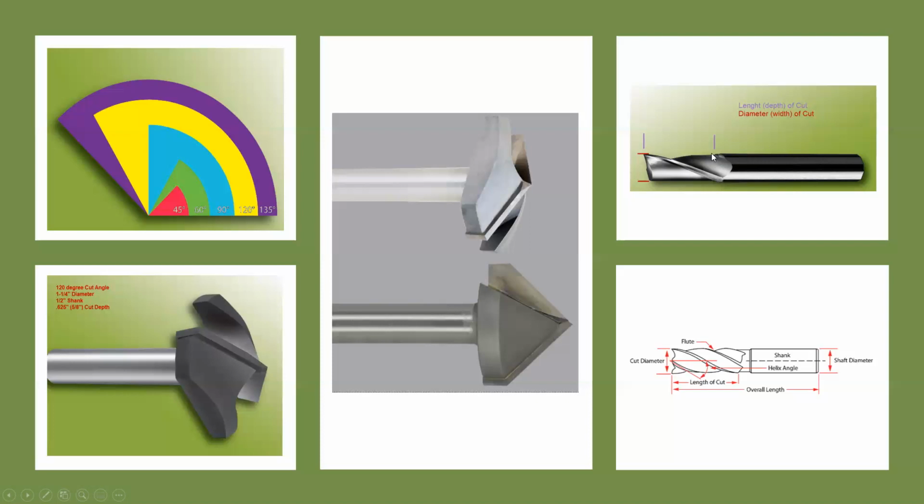Okay, but the cutting length or length of cut is always going to be the height of the flutes. And in some cases, you'll see cutters where these flutes may extend further up, but you can see that the diameter of the flutes changes, and they're just for chip extraction at that point. If the diameter changes and the cutting edge doesn't continue up, then that would just be milled surfaces to help eject the chips, and not necessarily what you would be considering as part of the length of cut.